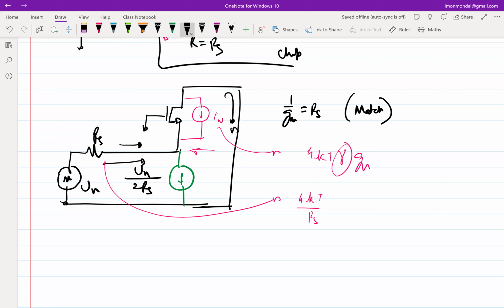Okay, so still fairly high noise figure, right? But still works. I am not disregarding any of these configurations. There are applications where you need maybe 6 dB noise figure, 4 dB noise figure. There are applications which are not very noise sensitive. For example, when you use your remote controls, right? Or even now everything has a remote which you can control an AC, fridge, TV, everything, right? So single remote does everything. Their noise figure requirements are not that high.